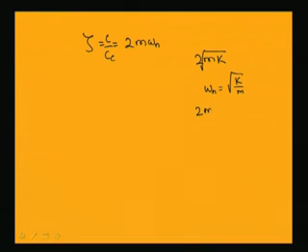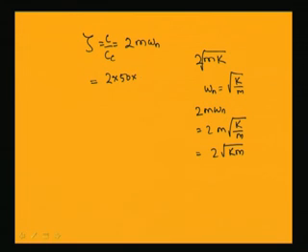So, 2 m omega n you can write equal to 2 m into root over k by m. So, this is equal to 2 root over k m. In this way also you can write zeta. Given the system parameters m, k and c, you can find zeta. That is equal to, now, 2 into m, with m equal to 50 kg, and omega n already you have found.